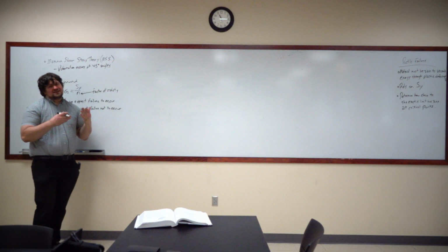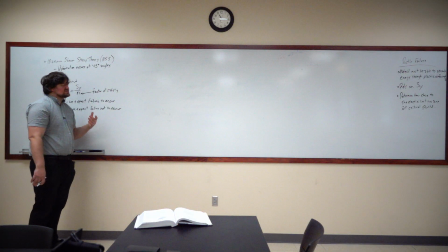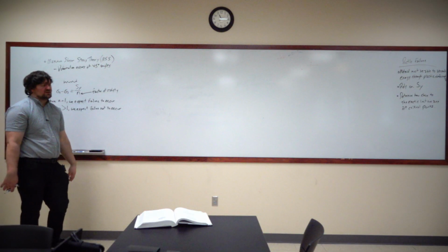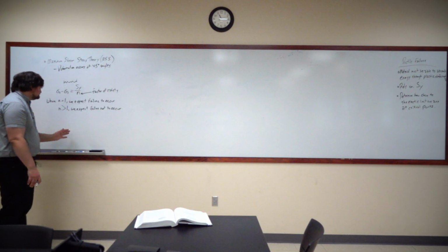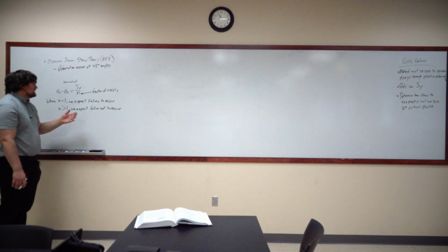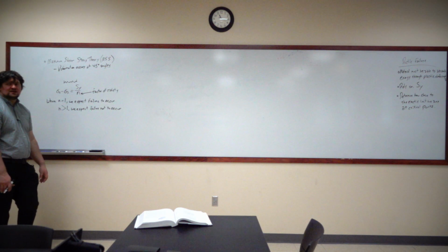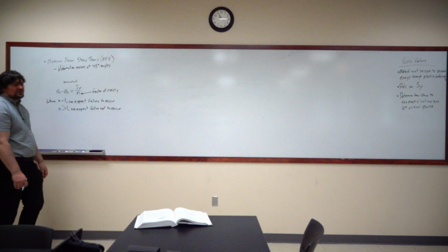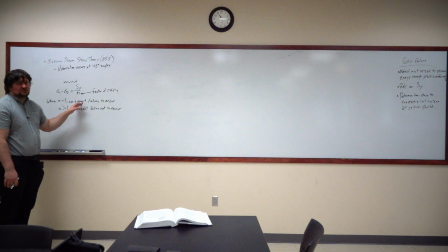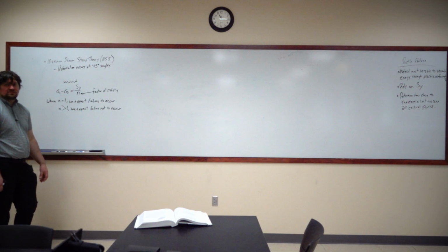Larger factor of safety, we don't have to be as certain about how the stress conditions are being applied. And it does give us a more conservative estimate too when we're trying to determine whether or not failure is going to occur. So conversely, if n is less than 1, we also expect failure to occur. It's just n is less than 1, the severity becomes bigger because you're almost guaranteed failure is going to occur. Like I said here, about 50% of samples would fail. The lower you get, the more and more probability you're going to have samples failing.